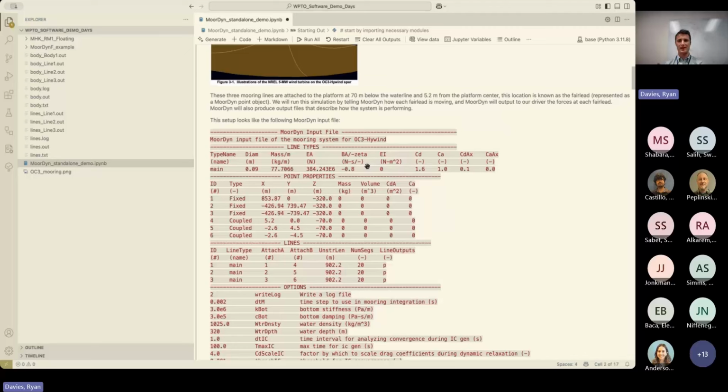And this negative value is actually representing a fraction of critically damped, where critically damped is targeting the natural frequencies that can typically be excited due to numerical instabilities. So a good value for this is typically -1 or something close to it. So today we'll use a -0.8.